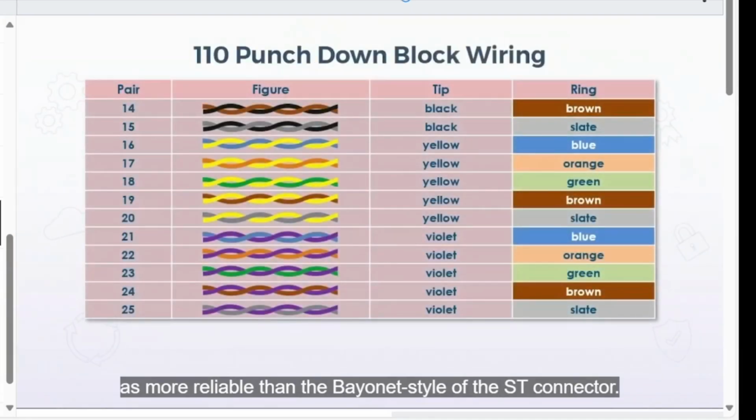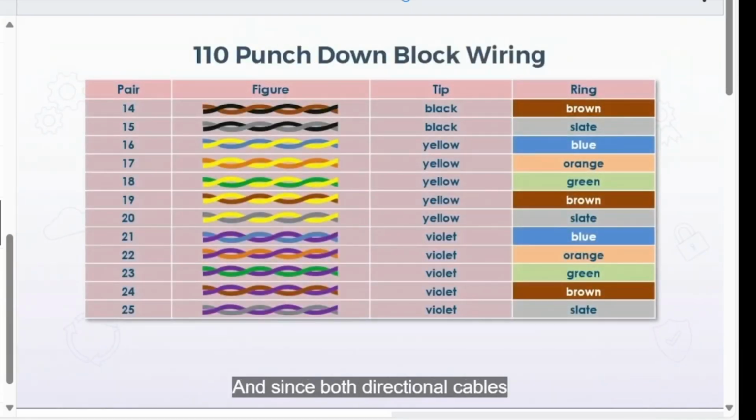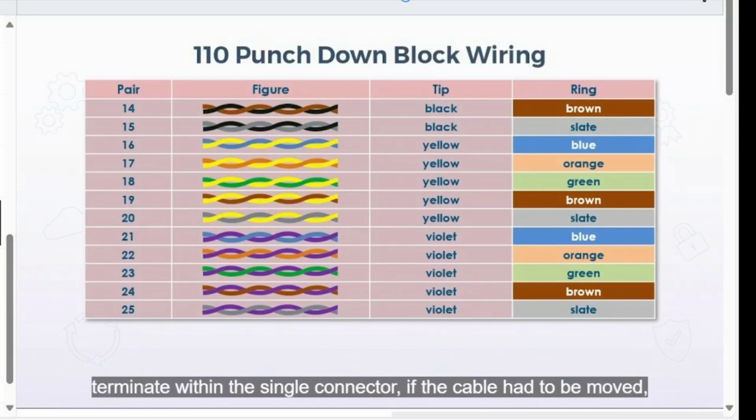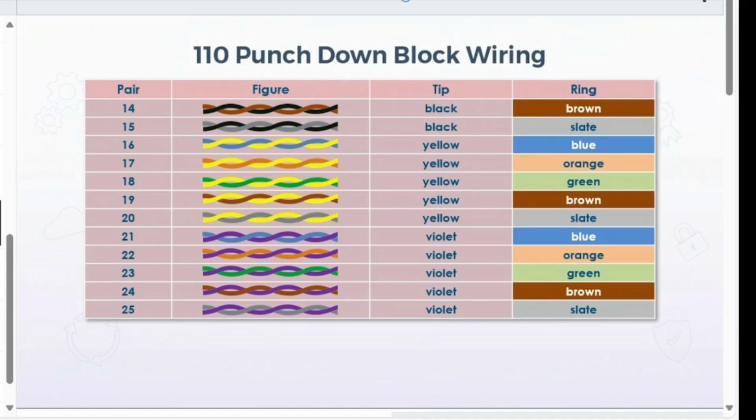So as mentioned, each bank or block accommodates 25 pairs or 50 wires in total. So if you are pre-installing that single 25-pair cable, you simply follow the wiring scheme as indicated, connect the devices on the other end of the cable, then leave it to the tenant to connect whatever they like. But the color scheme is a standard and should always be followed when pre-wiring a punch-down block. Again, each different set of colored wires are simply used for different types of wiring or different types of devices. But cables such as Category 5 and up for Ethernet and possibly Category 2 for analog voice would still be among the most commonly used.